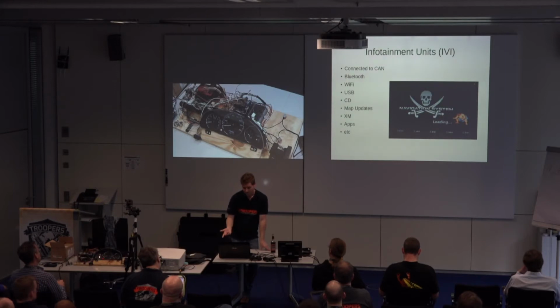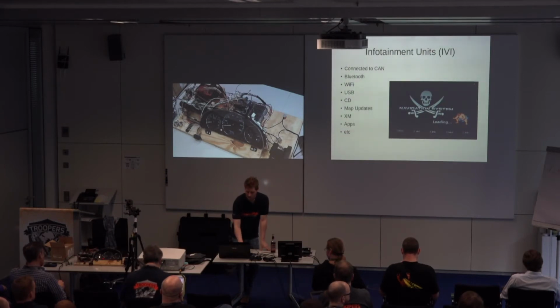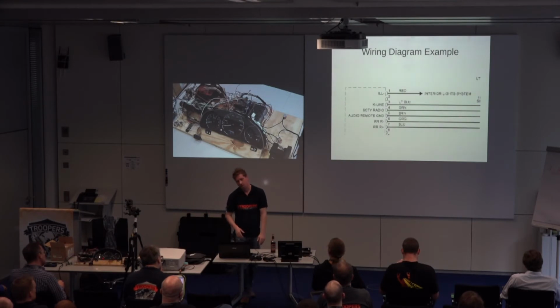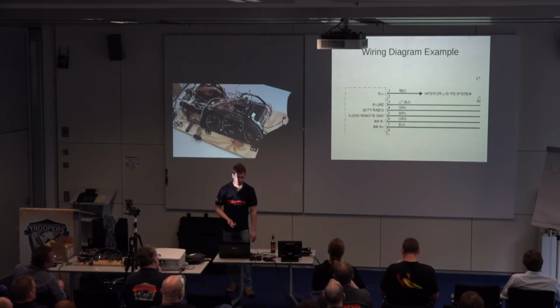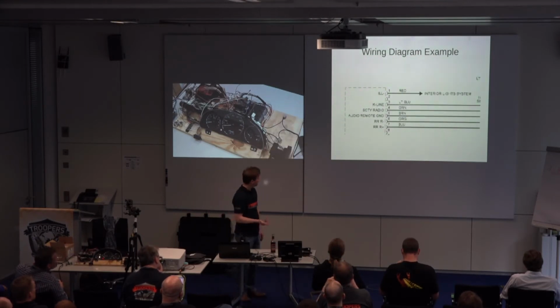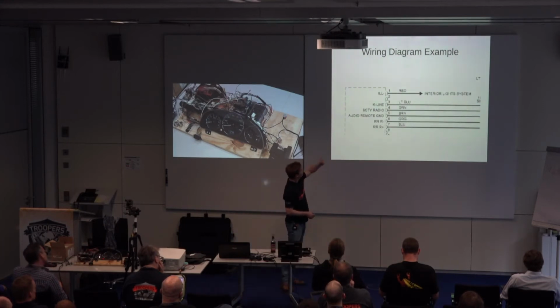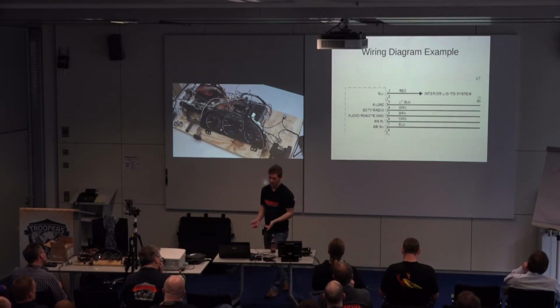And once you're on them, what you can do. If you have certain vulnerabilities, this is where they're going to come in. And so what bus you're connected to will really matter. Even without taking your radio apart, if you were to get a wiring diagram for your nav system, this one's for that unit actually, you can see the number 4 pin there is K line. It's not CAN bus, but it's similar to CAN.